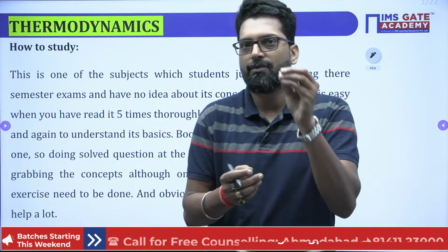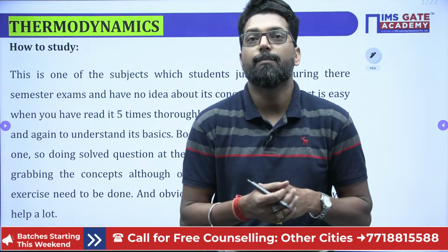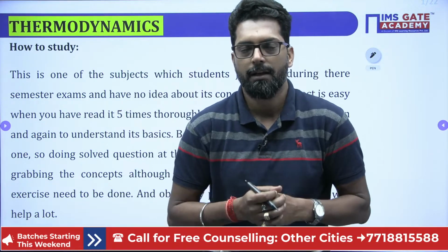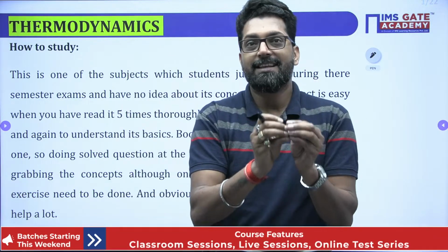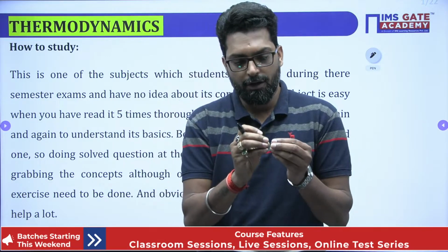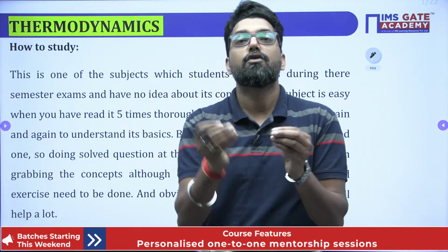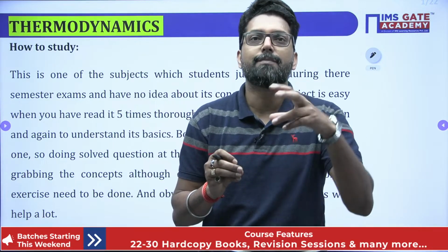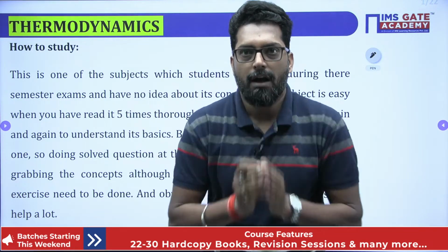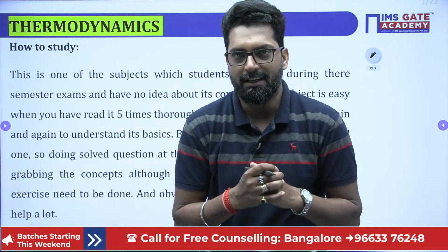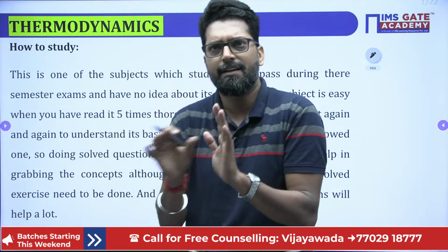One thing is very clear: the thermodynamic work or quasi-static work must be internally reversible. A reversible process must be a quasi-static process, but a quasi-static process need not be reversible, because there may be external irreversibility. The fundamental of quasi-static is that it must be internally reversible. What is happening externally, we don't bother about.